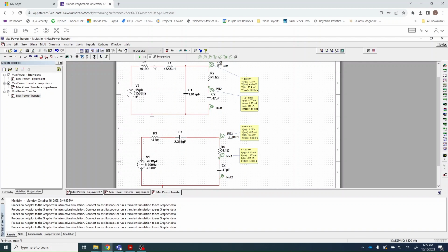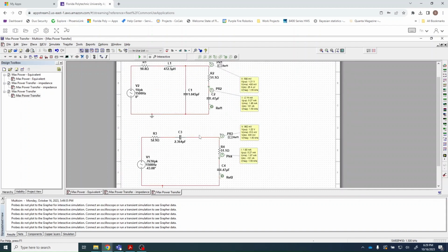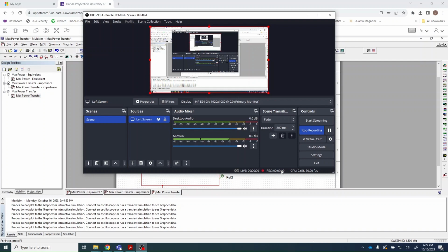So if you are working with your original circuit that you use for your Thevenin equivalent circuit, you can do so. Just replace your Z load with the element that you determined you needed in order to cancel out the reactance. So you are not obligated to use the Thevenin equivalent circuit. You could use your original circuit because they behave exactly the same as far as the load is concerned. So I know that was a little long-winded, but there's lots of little tricks to this lab, and now I'll turn to the experiment, and hopefully that will resolve a lot of questions.